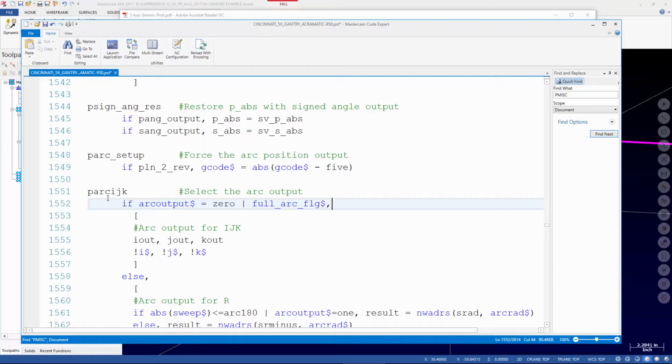Really, again, the shift value to me should account for any error or misalignment on the machine itself, and we should just be able to program it as if the center line were in the exact center line, and then the post will offset for us. So yeah, we'll take a look at that, and I'll show you the difference when we do our 5-axis trunnion setup.